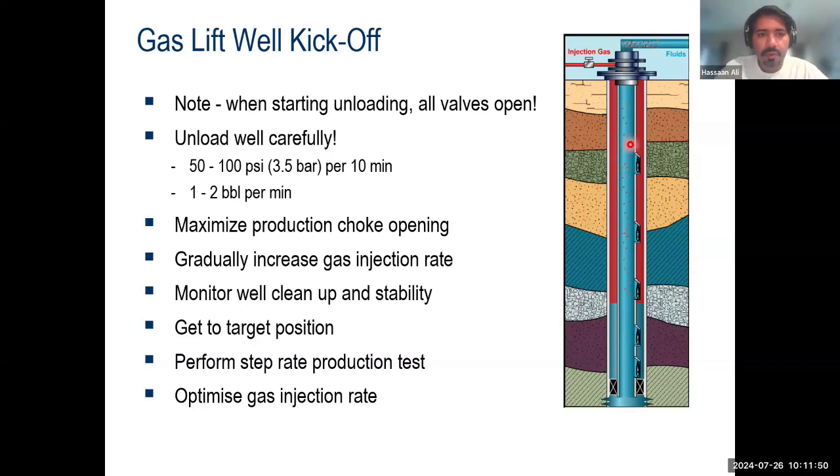So the first thing that we do is kick off, and usually kick off and unloading of the well are used interchangeably. Unloading of the well is usually one of the most critical phases of production engineering. The reason for that is that we have to do it in a gradual manner while taking into consideration that certain parameters are met, because if we don't do that, it can actually damage the formation.